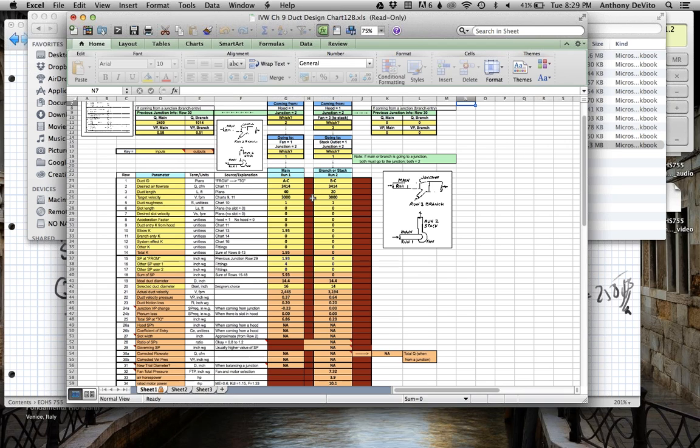Well, you've got to do a little bit of research. In other words, my reasoning on the vapor was that a standard lab hood usually has a face velocity of either 100 feet per minute for something that's not terribly hazardous. You know what I mean by the face velocity, the average velocity across the opening of that hood, 100 feet per minute. Or if it's something really hazardous, 200 feet per minute.